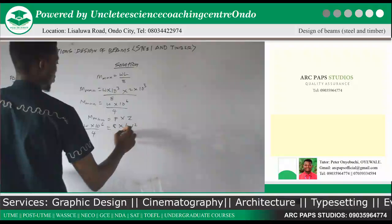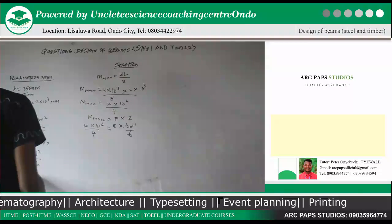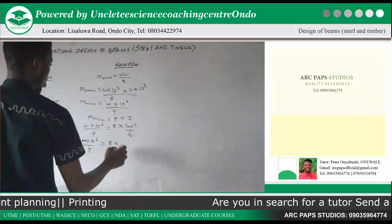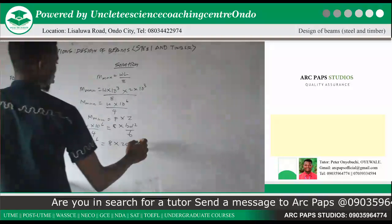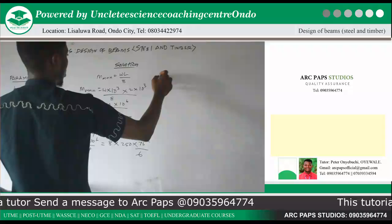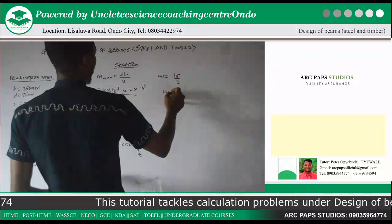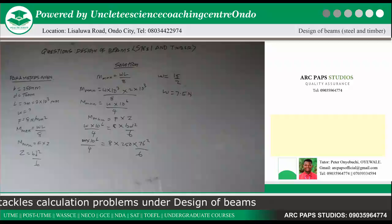Our F is 8 times our Z, which is BD square over 6. Now this is W times 10 raised to the power 6 divided by 4 is equal to 8 times our B, 250, times our D, which is 75 raised to the power 2 divided by 6. Now our W using a calculator will give us 15 over 2, and 15 over 2 is 7.5.